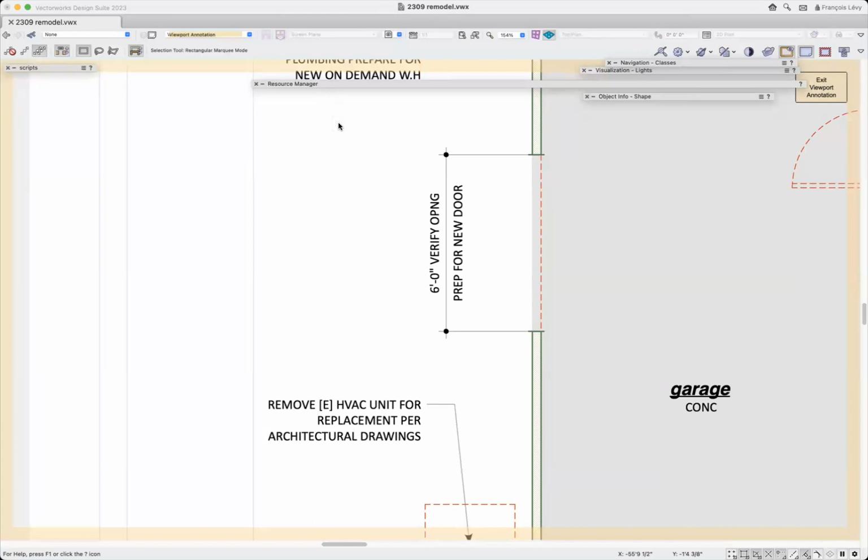The other thing about the floor, different horizontal surfaces, like if you're putting in a new floor that's either thicker or thinner or not level. Sometimes you're ripping out a tile floor and putting in a wood floor, or vice versa. So it's the same deal of the demolition classes and the adding components of the demolition class, which have to do with floors and horizontal structures, or ceilings that might be removed. Yep, that's right. So we typically model our ceilings either as floors or as roof faces, depending on whether they're vaulted or flat. And those get assigned to a demolition class as well.